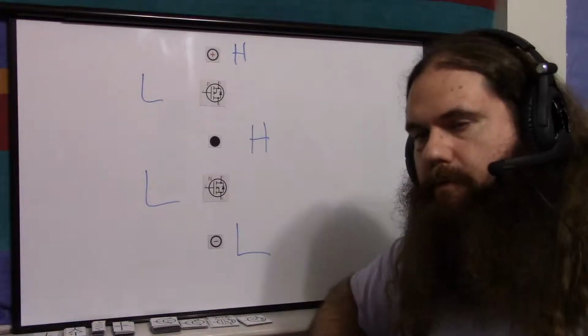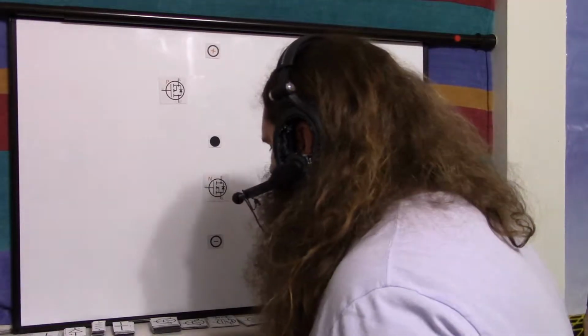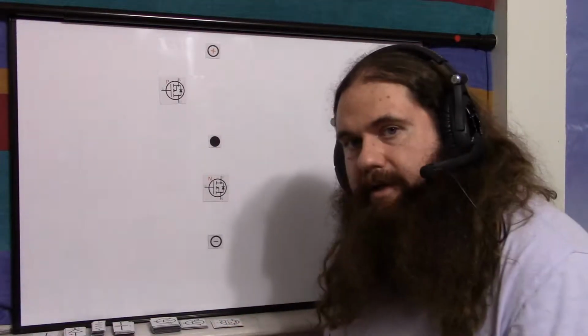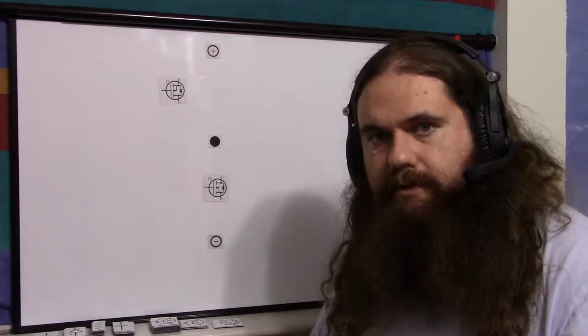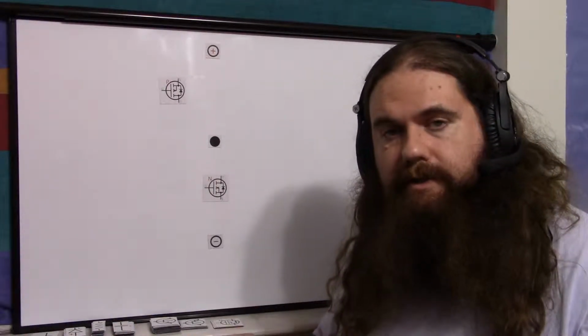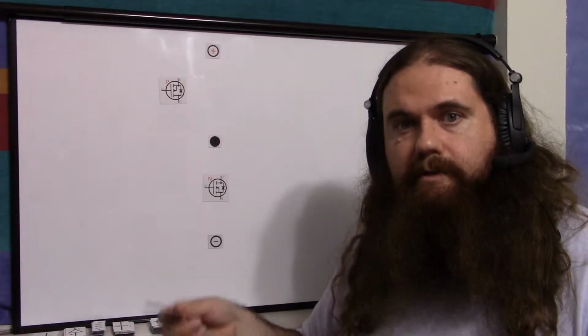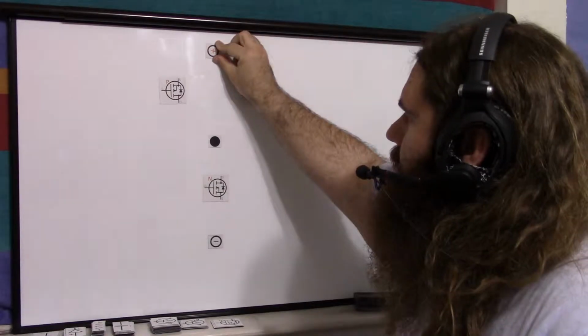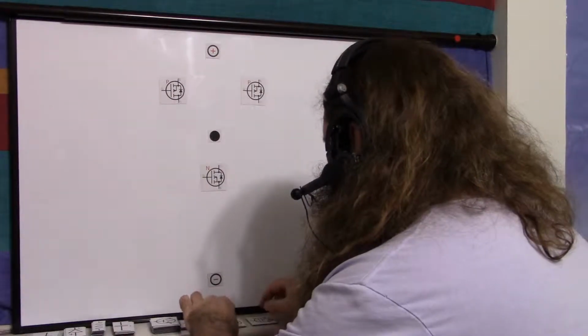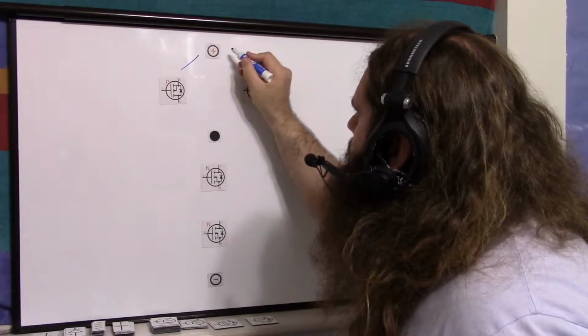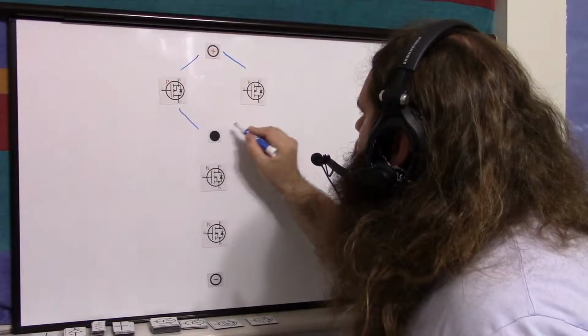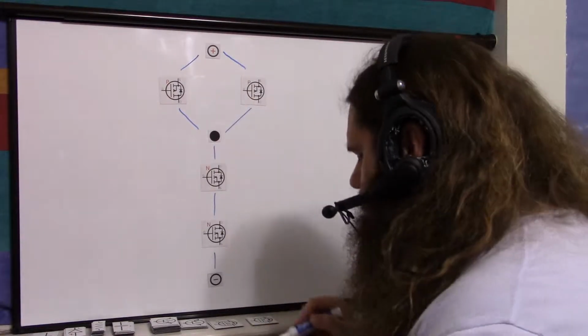And there's your inverter. Well, what about a NAND gate? This is where it gets tricky. So we know it's double. So a NAND gate is 2 NPN transistors in series or 2 PNP transistors in parallel plus a resistor. Here, because we know we need double, we're going to need 4 MOSFETs, 2 Ps and 2 Ns. And they will be arranged like so. The P types will be in parallel. The N types will be in series.